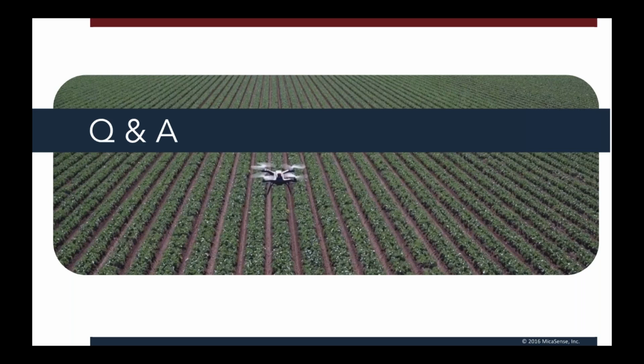Hi guys, this is Greg from Pix4D in the San Francisco office. There are a couple of different options for generating big projects, and it depends a little bit on what you mean by big in terms of area. The camera features are treated as a rig within Pix4D. So even though you're getting, say, 1,200 to 2,000 photos, they're not treated that way in the processing like the standard RGB camera would be. Each band is actually combined as a rig.